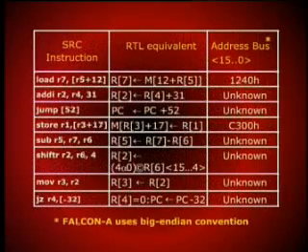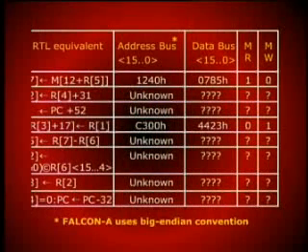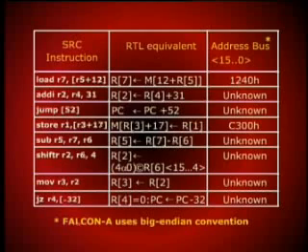Similarly, the next instruction, jump 52, in the form of RTL equivalent, says PC should be incremented by 52. In this case also, external buses are not activated, both our read and write signal for the memory are 0, and the data on address and data bus is of no consequence. Now you can just go through the next instruction, store, which is just the opposite of load.